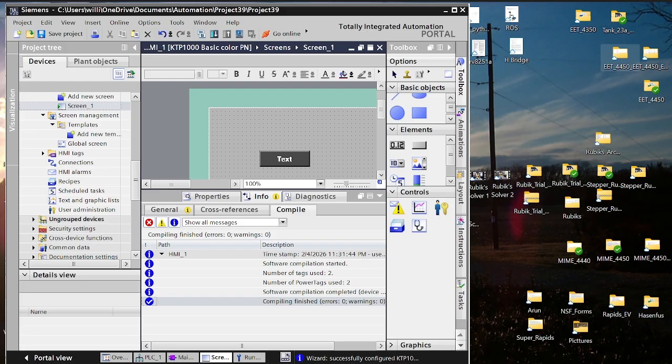Now I made a mistake in that it's a coil that actually turns on. I made it as a contact. I should have made it a coil. Coils are what turn on bulbs or light bulbs or lights, okay? So the bit can either be a contact or a coil, but a coil is what actually turns on a light. So I made a mistake there, but you can understand, make a coil on the right-hand side, and then that bit sets a light on your panel. It tells that it's running or whatever.